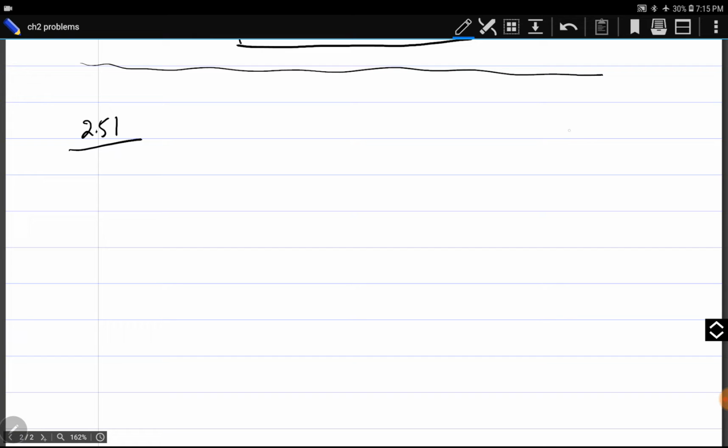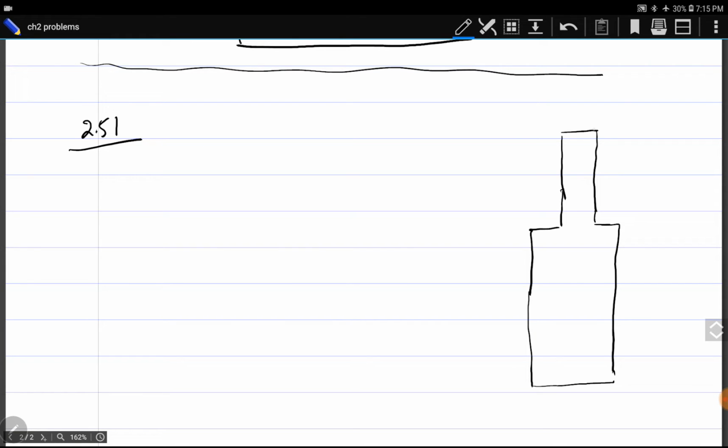In the first step, we have to remove one of the reactions. For example, I remove the reaction from point C, which I may call a redundant reaction. I will simply fix it from point A. So there will be a thermal elongation, delta T, due to the increase in temperature. This delta T is equal to the sum of elongations in member AB and member BC due to